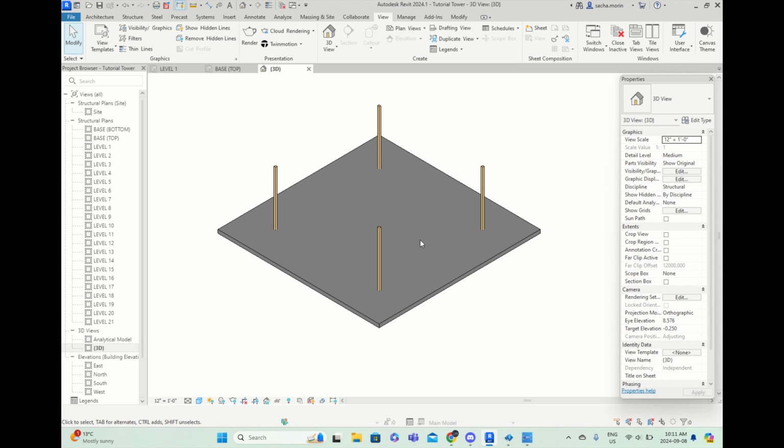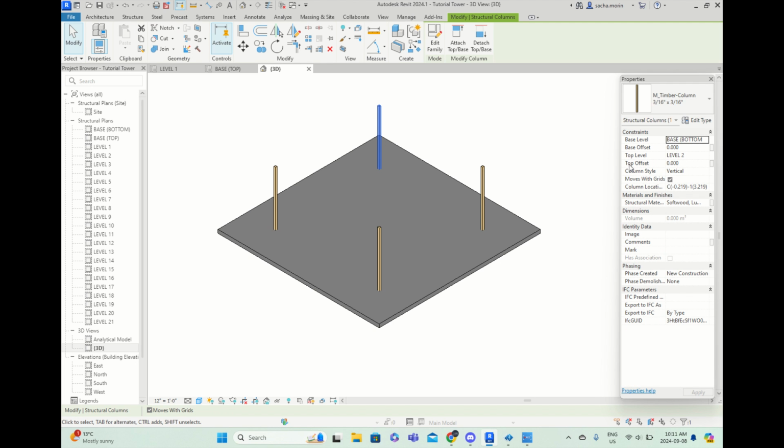Congratulations. So that is everything that we will learn in this second video. We learned a little bit more about the different types of line. So the first video we had grid lines, and now I just showed you about design lines. I showed you guys how to use those design lines to place the center of your columns where they have to be. And I showed you guys how to define your columns based on their properties with a little bit about the mirroring tool as well.